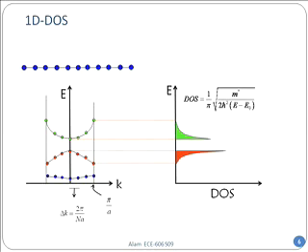Now, there will be a corresponding similar 1 over E, but this time E going below, and then same for the blue one. And one thing you realize is that this shape must be there because the area under the curve, density of states multiplied by the width of this region, must be equal to how much? N, right? Remember, N is the total number of states I have. So therefore, if the band is very skinny, my height, the density of states, must be larger than before, right? And you can easily see that from this expression.